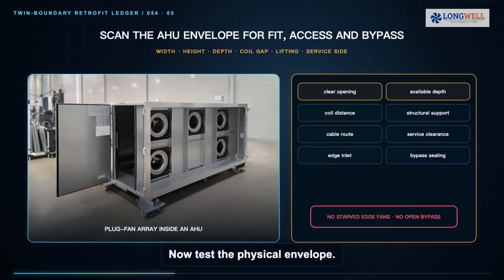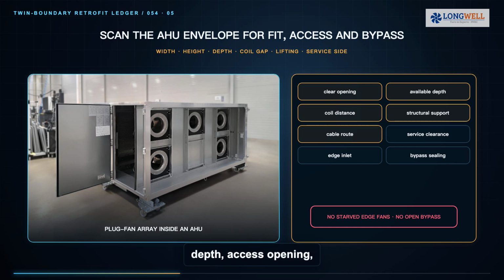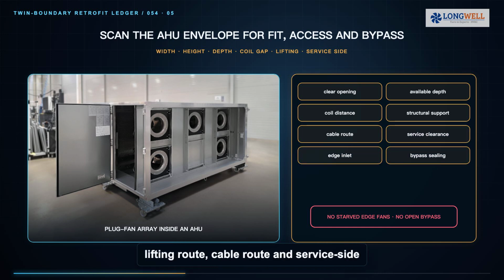Now test the physical envelope. Measure AHU width, height, depth, axis opening, coil distance, floor or rail strength, lifting route, cable route, and service side clearance. Divide the face into modules without starving edge fans or creating a large bypass path. The frame and blanking plates must seal the fan section, while each module remains removable. A smaller footprint is useful only when inlet conditions, discharge mixing, and maintenance access remain acceptable.